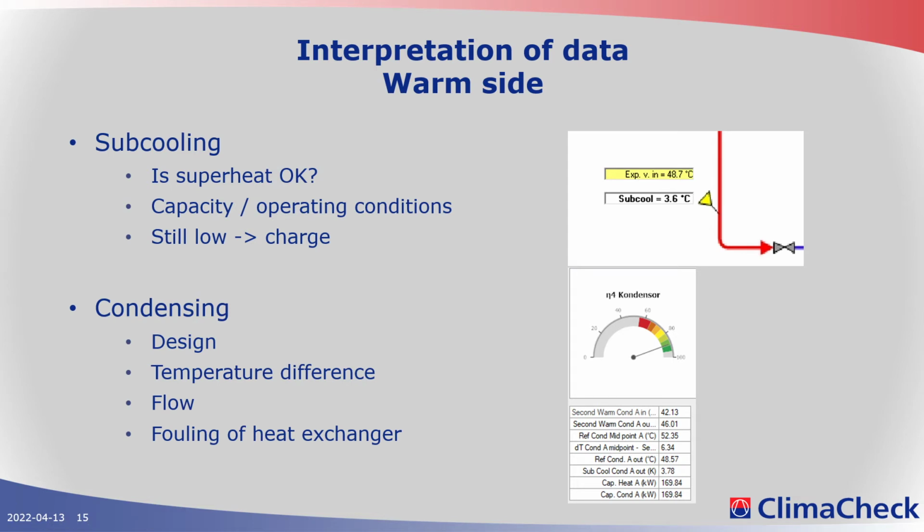Again, capacity. If I have low capacity operating, my subcool will decrease in most systems. So look at your system. Preferably you have recommendations for what it should be.